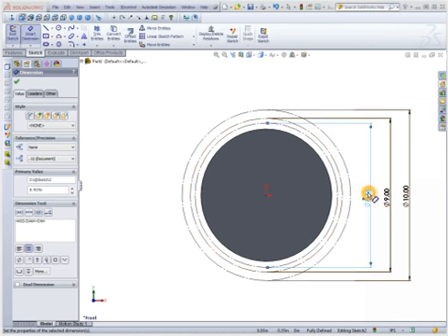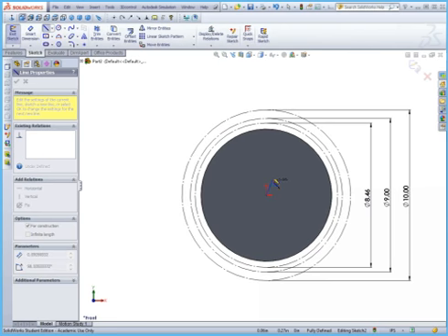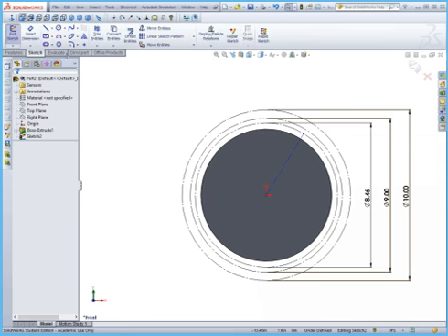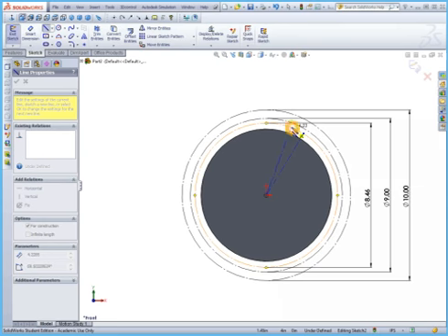We're going to use the base circle to actually draw the involute curve, and the process we're going to use is the tangent process, where we draw multiple lines tangent to that base circle, and we draw a spline on the end of those. Now, each one of those lines is going to be twice the length, and to generate those lines, we're going to draw segments first. Starting at the center of the gear, we're going to use a center line, basically a construction straight line, and we can go straight out to the base circle. And now we don't want to snap to anything because we want to make sure that these can float around that line. So I'm going to draw 1 line, and I'm going to keep drawing lines. Probably need about 4 or 5 of these at least.